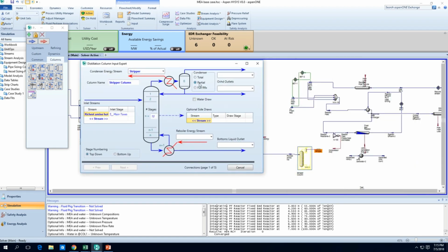We will have a full reflux condenser, maybe either that or a partial condenser. We can actually just edit that later. So we have gas overhead, and maybe some water that we can condense. So stripper duty is here, condenser duty, reboiler duty, and lean amine.